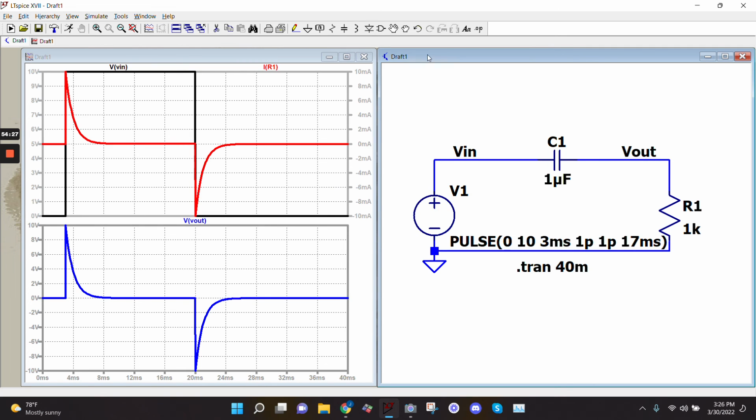Any questions? Do you have a question? No, I get it, because although they both rise, the V out dissipates. But then in order to reach zero, it still needs to take 10 distance. So it just quickly dips down and comes back up slowly. That's right. It's maintaining equilibrium, basically. And the amount that it dips down is the same as the amount of change in V in. Exactly, because it needs to keep the voltage across the capacitor.